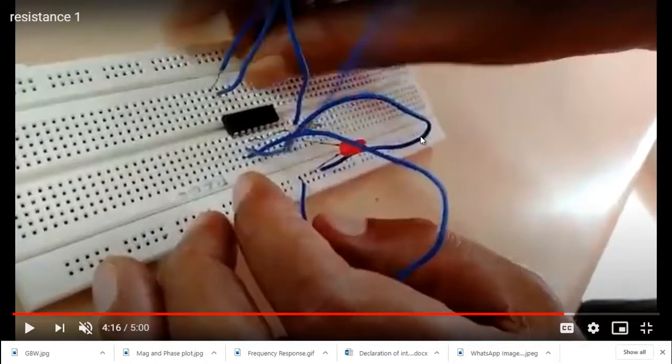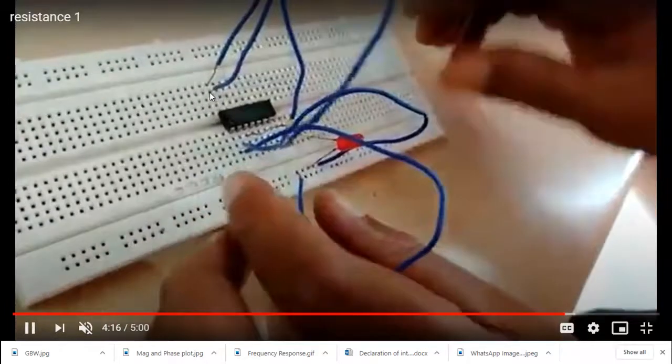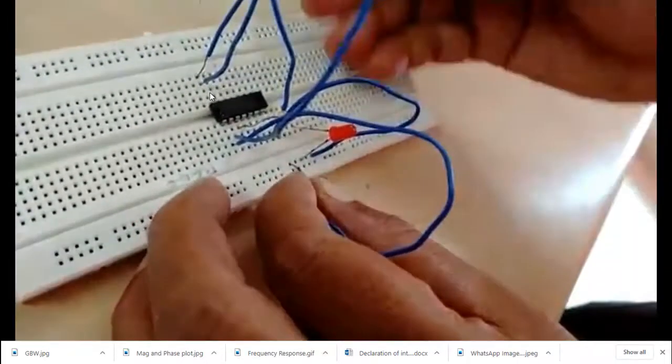All are connected at the same potential. Since this LED is connected in the second half of the 50 points, those second 25 lines will make a potential. So from the 7th pin, a loop is already connected to minus VCC, and the negative of your LED is also connected to minus VCC. So that is 0 for us, otherwise it would be ground. Here one of the inputs is connected to ground, and the other input is available at the 14th pin of your 7408.